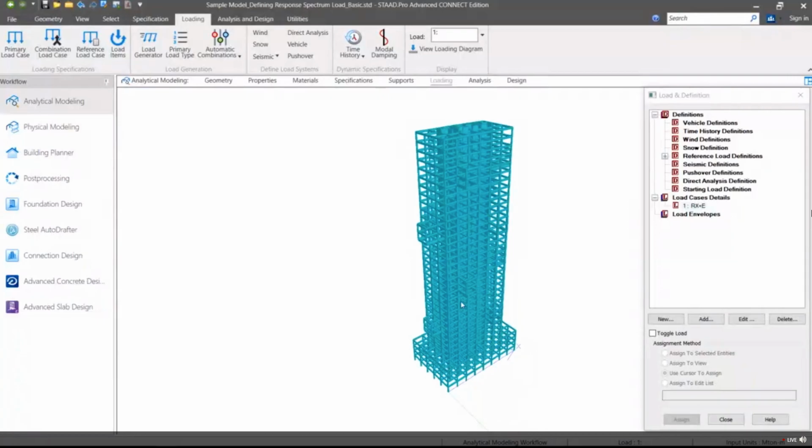According to clause 12.3.4.2, for seismic design category D with extreme torsional irregularity, it should be 1.3. And if the structure is torsionally stable, still it should meet two other criteria before reducing the value. So we need to first check whether the torsional behavior of this structure is okay or not.